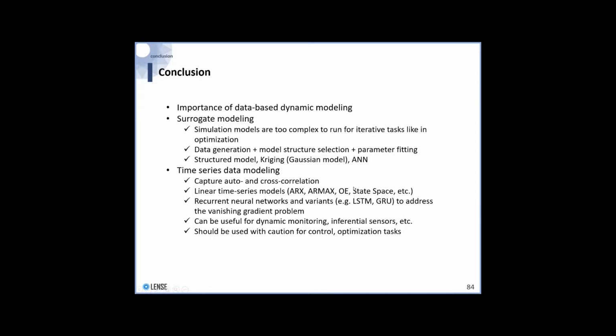And you may want to look at state space, subspace models. And then if you desire something that would capture nonlinearity, then you can go for recurrent neural networks. But that's a leap in complexity. I want you to know that going from linear to nonlinear, now you have a lot of parameters and a lot of things that can go wrong, actually.